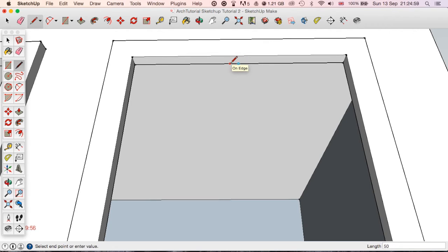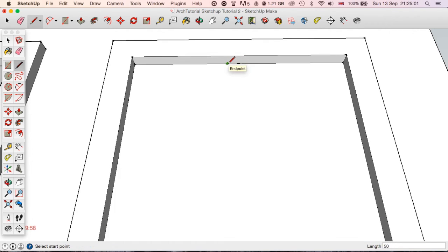Now by going off by 50 mil one way, you'll see it automatically fills in the window, but we can just delete that later. Then going back to that center point, and going 50mm the other way. Then all we do is take 2 lines from those 50mm points, either way, and you'll see we've created that small box.